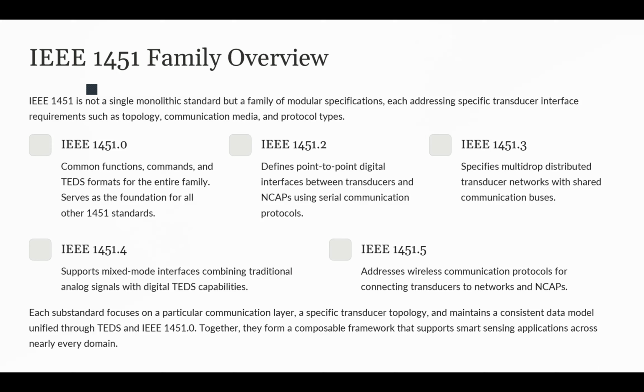Part 4 is the mixed-mode interface, which combines the traditional analog measurement lines with the digital TEDS metadata. So we have the ability to take legacy analog transducers and make them able to participate in smart sensor networks. Part 5 covers the wireless communication protocols, which define how TEDS can communicate wirelessly with the NCAP.